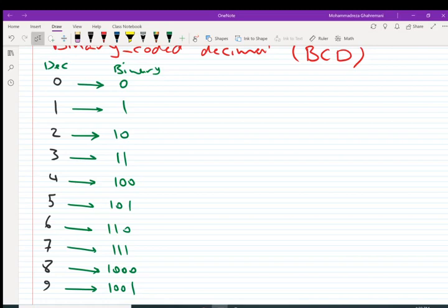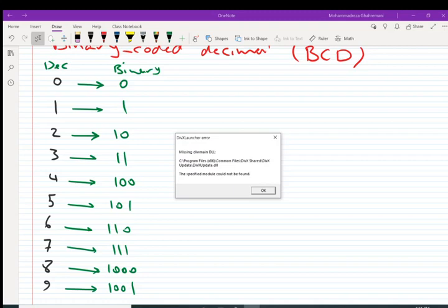And it is not a good idea to use different coding lengths. So it's not a good idea to use 1 digit, 2 digits for some decimal numbers and 4 digits for other decimal numbers. So here we can use a new numbering system called BCD, or binary coded decimal, in which each decimal digit from 0 to 9 is represented by a fixed number of bits.